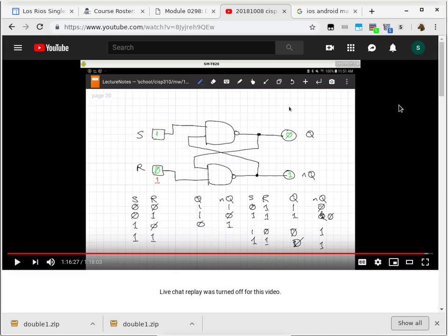All right. So last time we were talking about the SR latch. The SR latch is the most basic memory device because there are two input pins and two output pins. For the most part, you can look at it as only one single output pin, because /Q, or not Q, NQ, is not really usually used. Sometimes it is, but most of the time it is not. Most of the time it's really just the negation of Q itself, so it's not particularly useful.